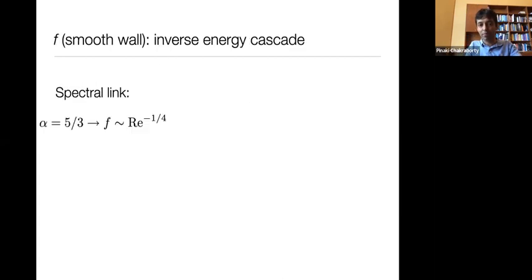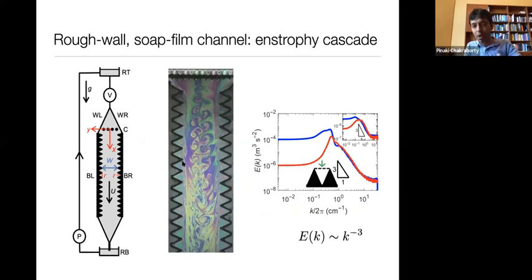Now let's consider the rough one. When we now talk about the rough flow, we are interested in the interface between the rough wall and the flow here. The no slip boundary condition is going to pertain to the region over here. So therefore, my viscous sublayer is going to be coating this region over here. And the interface that I'm measuring, where I'm measuring the shear stress, is going to be dominated by turbulent flow. So I'll have to, first of all, make sure that the viscous stress doesn't play a big role. I have to get a good profile of the Reynolds stress all the way across.